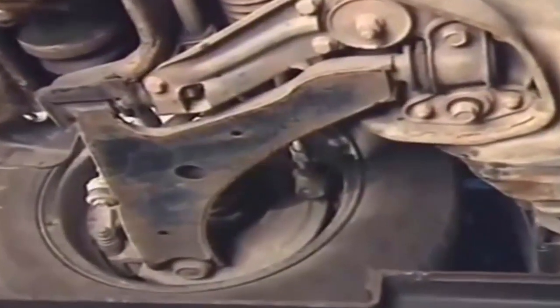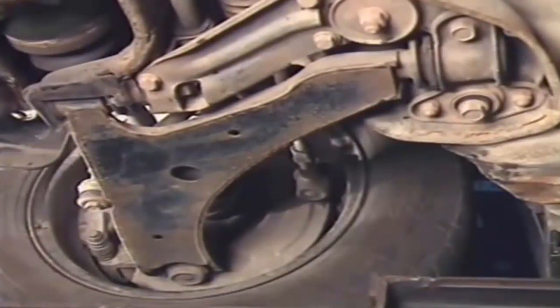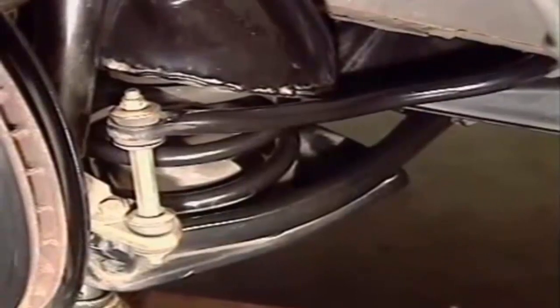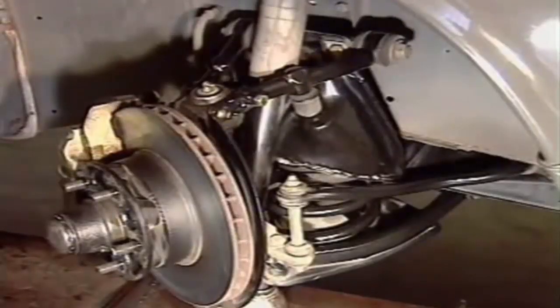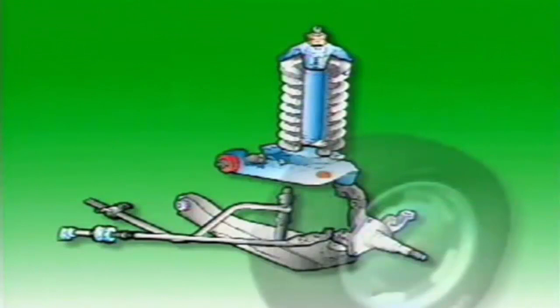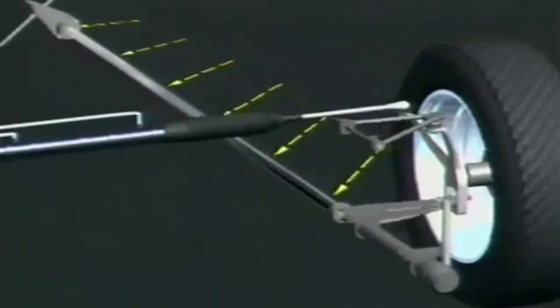In this front-wheel drive suspension, the control arm is a wishbone shape with two widely spaced mounting points. This prevents backward and forward movement, so a tension rod is not needed. Wishbones can also be used in a parallel link system. They can be used in pairs with the coil spring between the lower wishbone and the suspension crossmember. Alternatively, the upper link may be a wishbone with a coil spring mounted above, combined with a single pivot lower link located by a tension rod. On some vehicles, a torsion bar provides the springing medium.